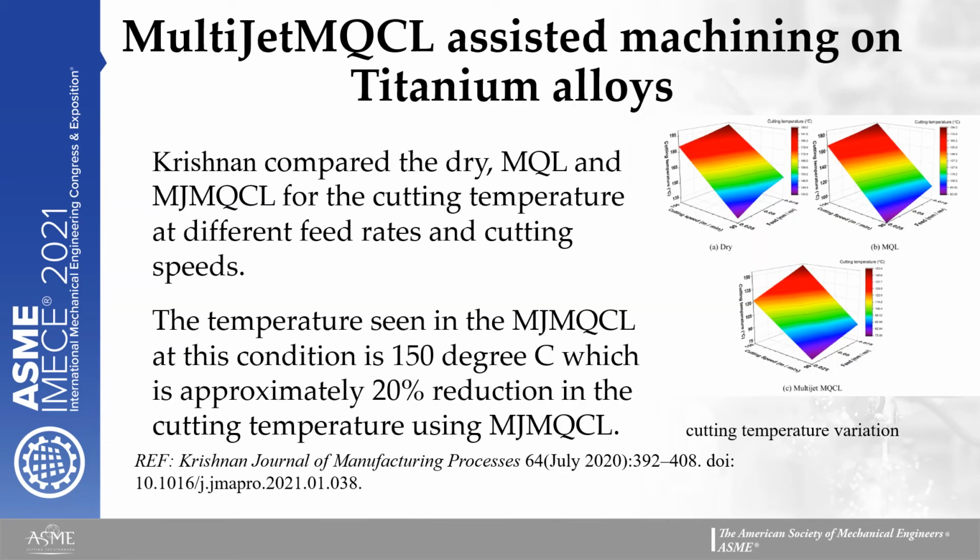In another study, multi-jet MQCL assisted machining of titanium alloy was investigated, and the performance was compared against regular MQL and dry cutting. The study revealed that with the multi-jet MQCL technique, the temperature was reduced by 20% as compared to the conventional MQL technique.